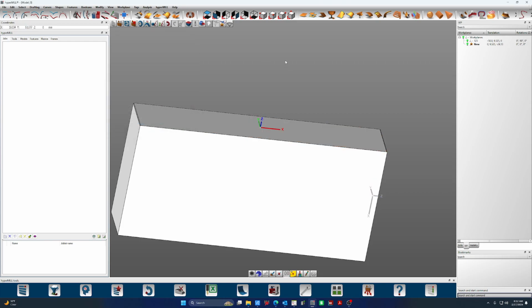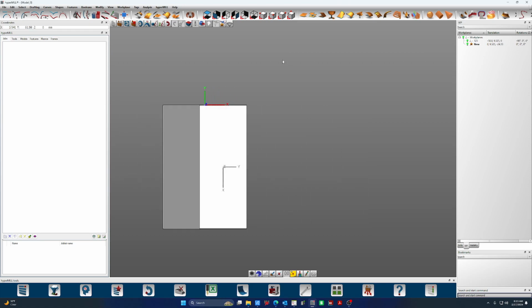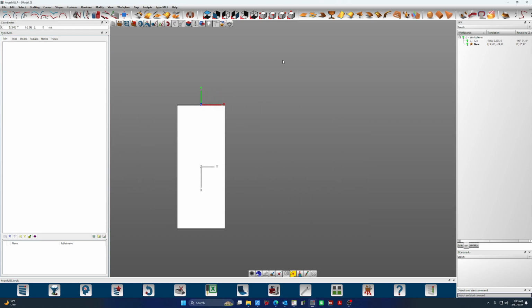And then quickly, I want my view to actually be normal to that front plane, or I want to look across sort of the bow of the plane that my work plane's sitting on. I'm going to just quickly tap the Alt key and X, and it's going to have rotated around that. And when I Control 1, my view is normal. And I could turn that around Y as well, Control 1. I can do it around Z as well.